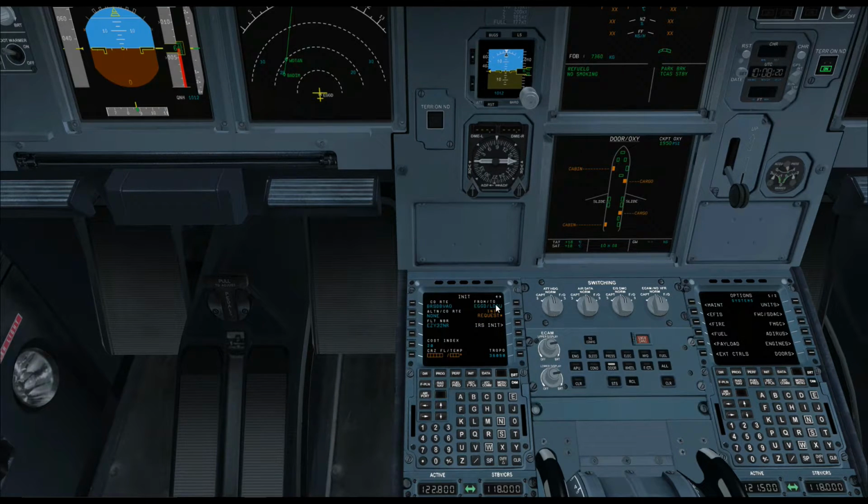and it's taken us from Bristol to Dubrovnik, and our alternate airfield is Lima Yankee Papa Golf. Cost index today, according to our flight plan, is 10. Estimated cruising level, flight level 370, and the temperature for the cruise on our flight plan is showing -53. Tropopause 36900.